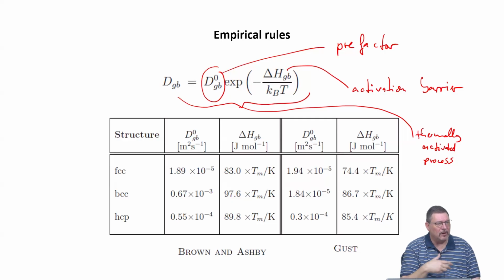So if you are working in an environment where you need to design a certain annealing treatment or get a first shot at an unknown system, you can use these parameters to calculate what roughly will be the grain boundary diffusion coefficient at a certain temperature, because you plug in the real temperature here, and then you can derive the numerical value, and so you can do a first experiment, and that will show you, is this rule of thumb applicable for this system, or is it rather not applicable? But the details will vary a lot from system to system.